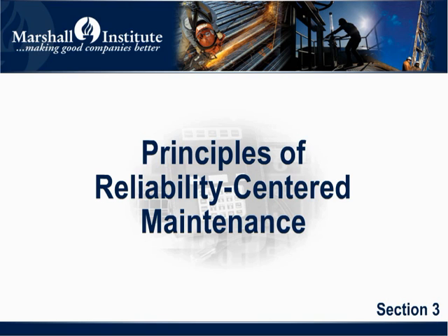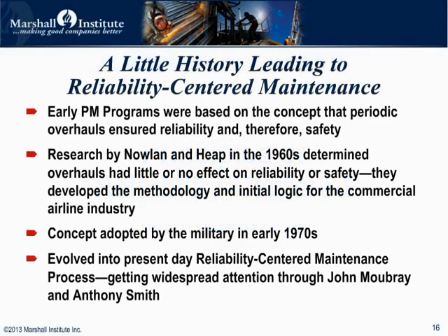Maximizing asset reliability depends on the application of the concepts of reliability-centered maintenance, so it's important that we understand the basic principles of RCM. Prior to the development of the RCM methodology, it was widely believed that everything had a right time for some form of preventive maintenance, usually replacement or overhaul. A widespread belief among many maintenance people was that by replacing parts of a product or overhauling it, the frequency of failures during operation could be reduced.